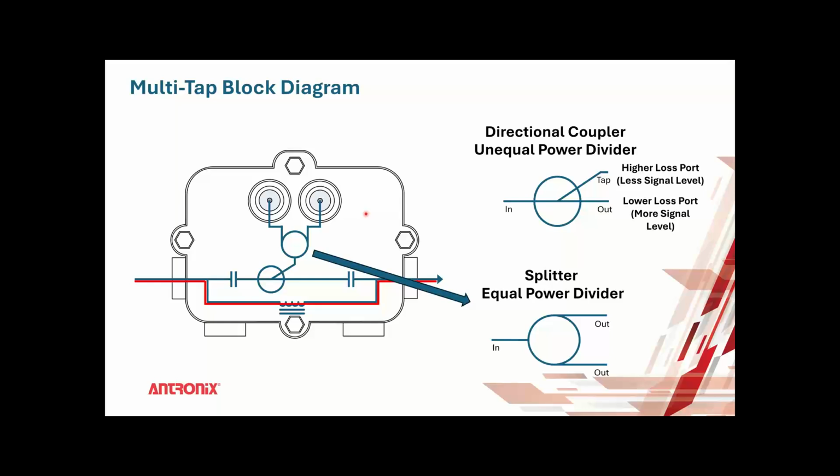So I have a question on this slide, Neil. Can you tell the audience what would happen if that RF choke was missing for some reason? If the RF choke is missing, then there is no AC going down through the tap. RF may still be there. There's the capacitor here, RF goes through the tap. You can have RF, but if that choke is missing, you cannot connect an AC device. AC is not going to be going through the tap into the output.